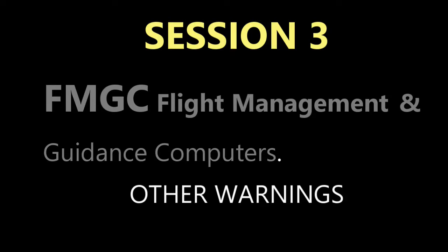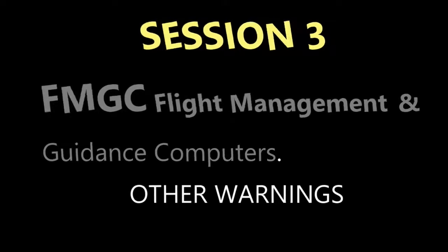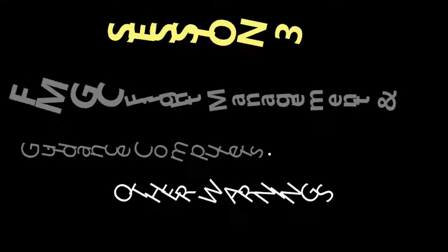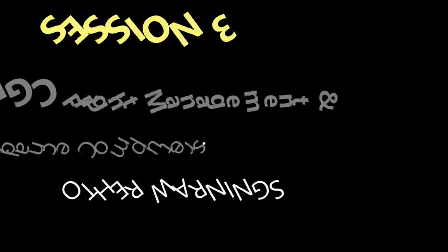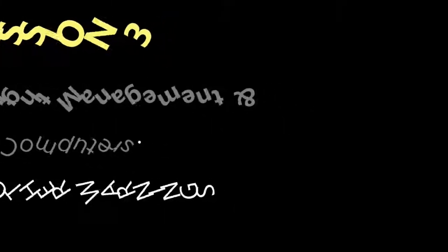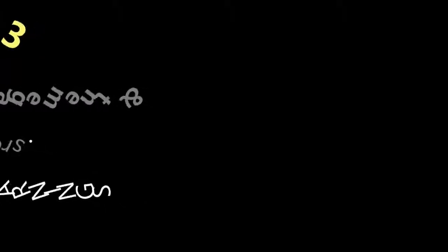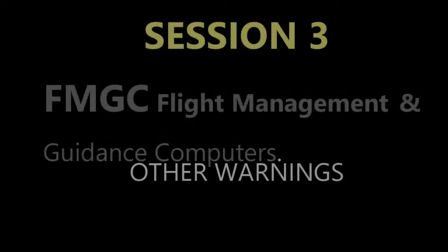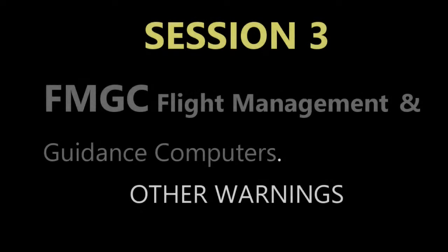Okay, and then autopilot, you'll have a warning for this one. The autopilot loss, again, is kind of similar to what I mentioned earlier about the first condition. If you have the first condition where you take over with a push button, you also have one where it's any other reason. You're going to have number one. Let's say you take action on that takeover push button. Then there's going to be a red master warning light that's going to flash for so many seconds. And there's also going to be a red AP off message that's going to be shown, and that'll show for a little while. And then there's also an auditory sound. So there'll be a sound there that will come on.